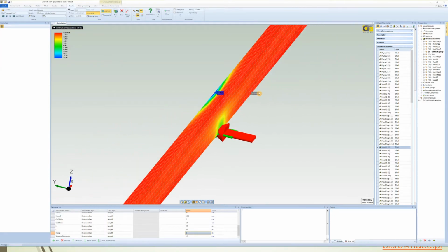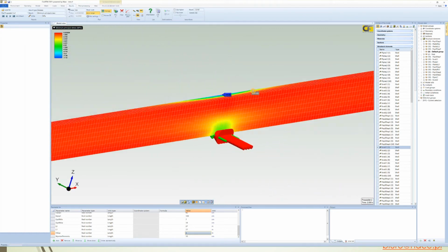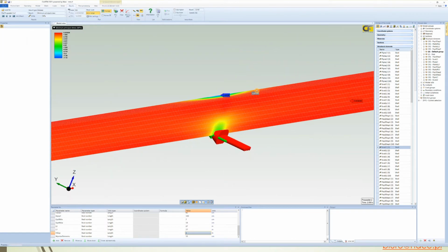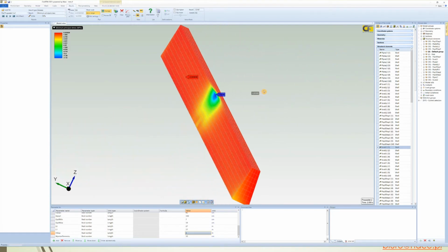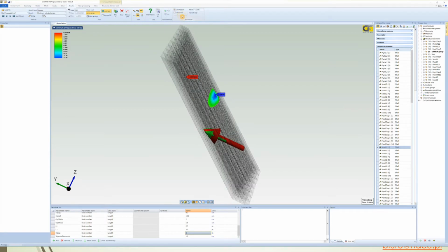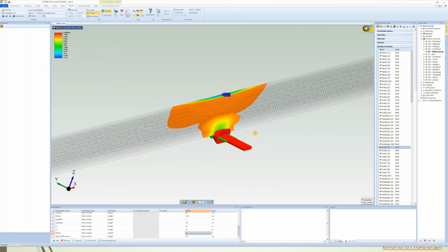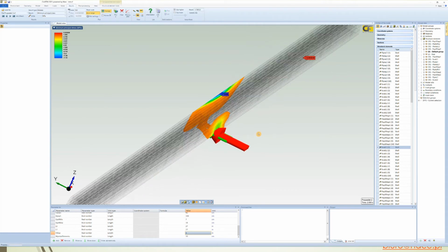Well, just plotting the minimum principal stress for tension and also the maximum for compression. Here you can see the stresses due to the impact on the bottom and on top, where you can add different levels for extracting different plots. You can see where those stresses are related. Also, these are clipping options for results. In this case, for one web of a T-beam, you can see the results here.